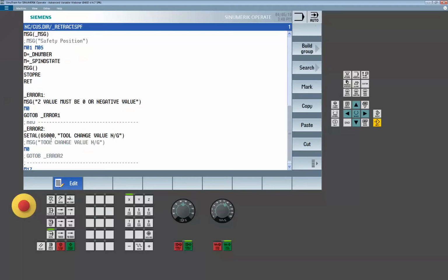The physical alarm, like I was doing the set alarm command here, there is a way to do a set message command, and that would also allow you to continue on. So yes, we do have ways. I could just do it in the way I build the structure of my logic to allow me to continue through and just push up a message.